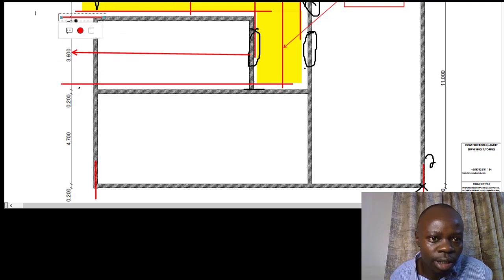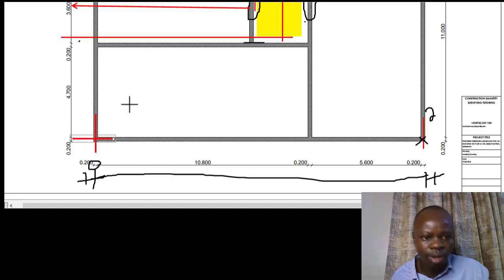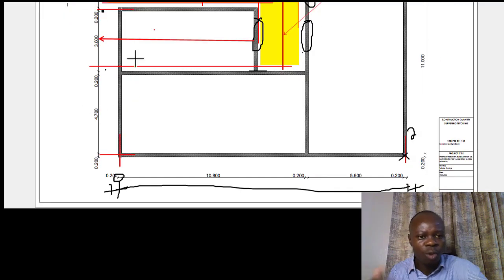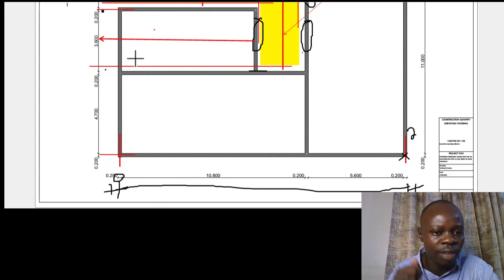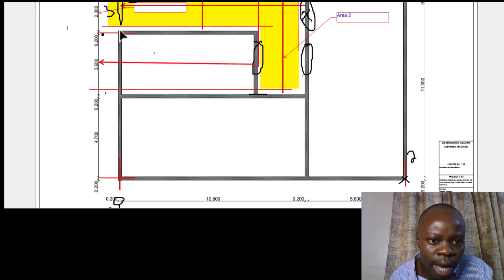Leave alone that it's not from the center the way I would require it to be. I want that also at the center there, and the same thing happening to this particular part. So we take the full length. Of course, we've taken the full length from the external faces of the external wall. Okay, when we do so, then we need to subtract half the wall to the top and half the wall to the bottom.